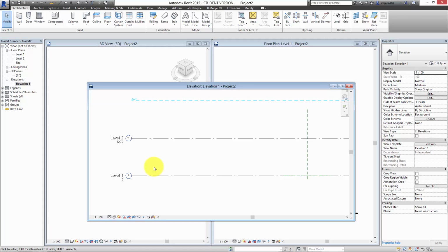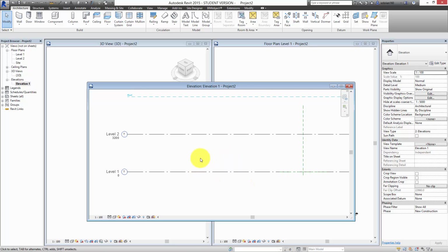If you've got a floor that's made up of wood and some kind of sound insulation layer, and then some kind of timber layer on top of that, all of that is underneath this level 1. So you're always going from the top of the floor to the top of the floor, and that's a key thing to remember, because if you don't figure that out, your stairs are going to go a little bit strange. At the moment, the levels are set to 3.2,